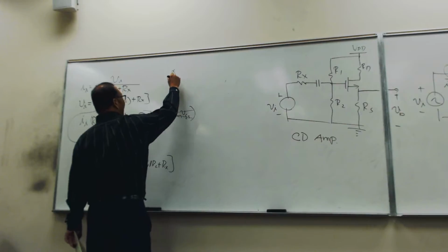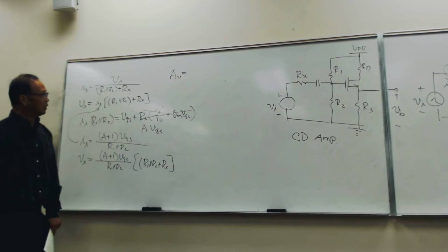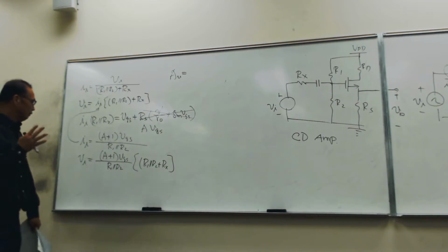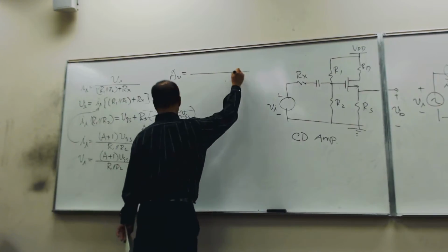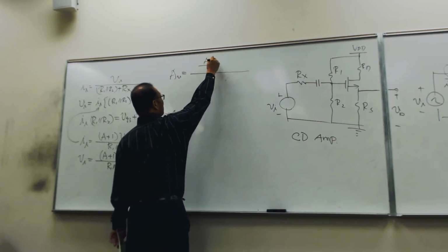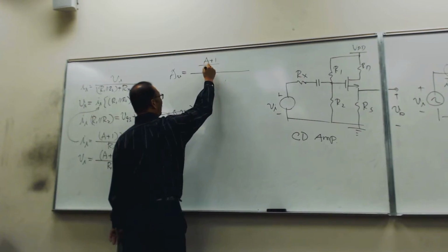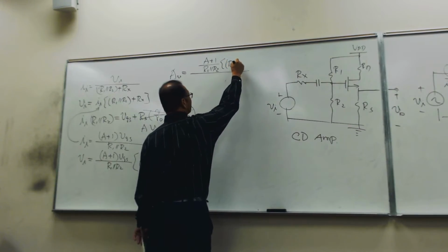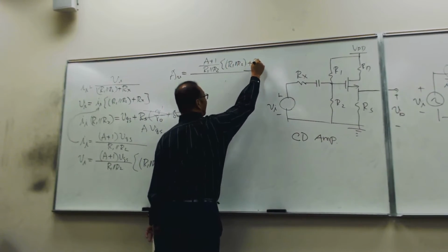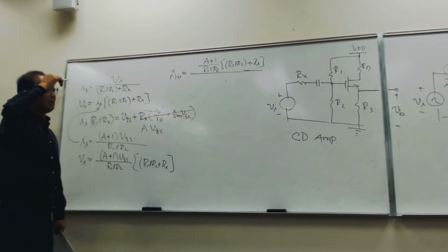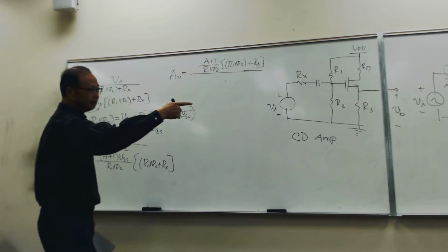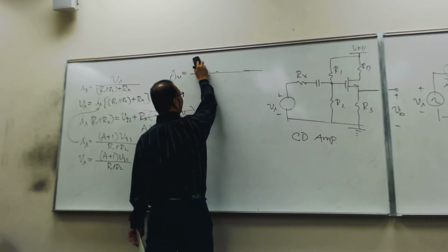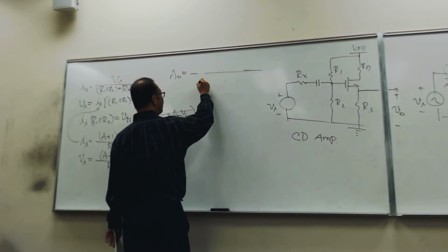Okay, then now I can take the ratio, right? V sub O on top, V sub I on the bottom. So VGS will cancel, right? So we get A plus 1 times R1 in parallel with R2, over R1 in parallel with R2 plus R sub X, right? Divided by that. This V should be on the bottom, right? Yeah. Okay, so it's on the bottom.